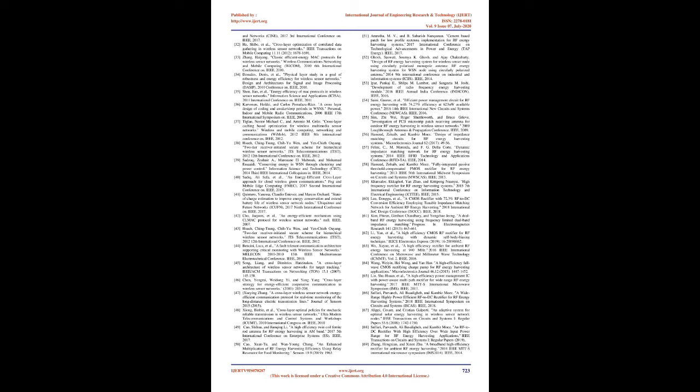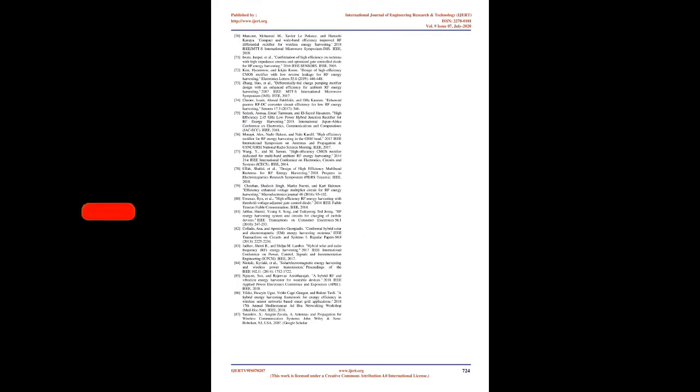Umeda et al., 2014, proposed rectifiers using gate-controlled diodes, GCD, with the varying threshold voltage, VT, of the MOS by ion implantation, integrated with 0.18 µm CMOS technology. The DC values of the gate-controlled diodes showed that the turn-on voltage of the GCD is less than the voltage of the Schottky barrier diode, SBD.